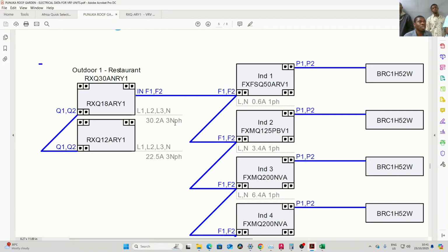Let me try to explain this. For our normal lighting, what is the cable size that we use? Yes, 1.5 mm. Do we all agree? What about for sockets? Now, if you use 2.5 to connect a light, will it work or not? Nothing bad will happen, but what is the minimum? 1.5.